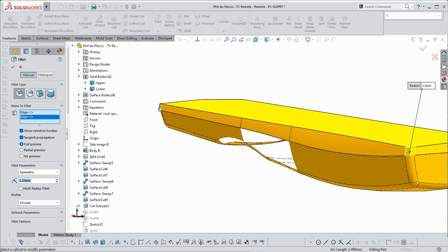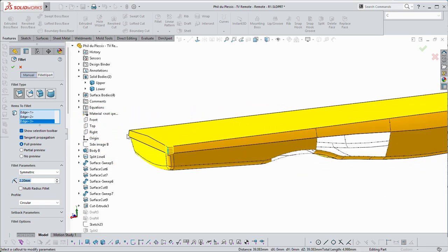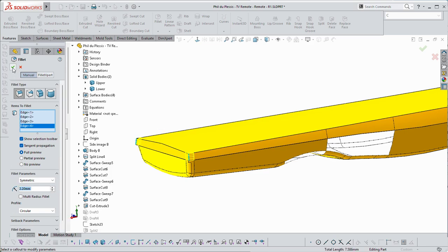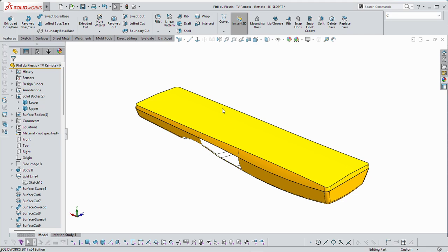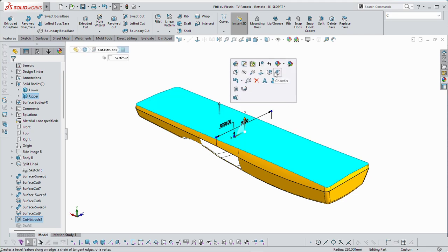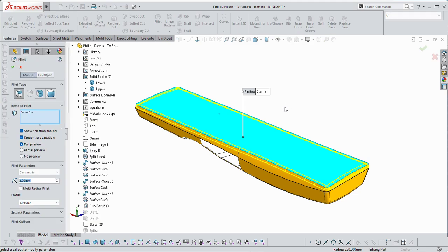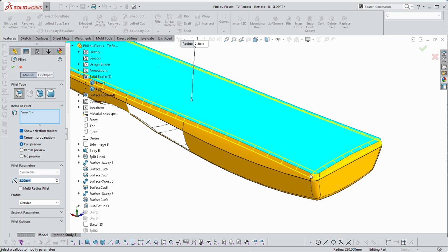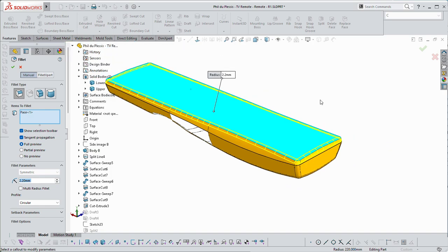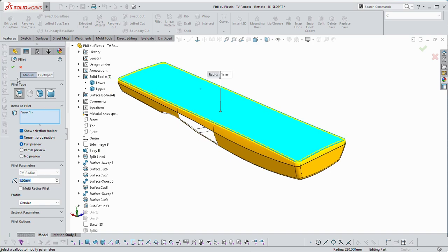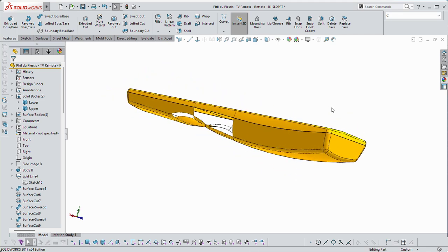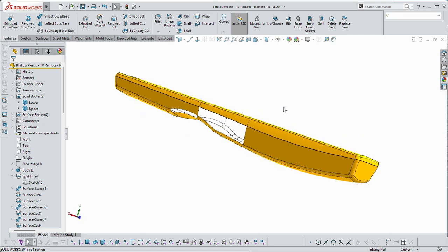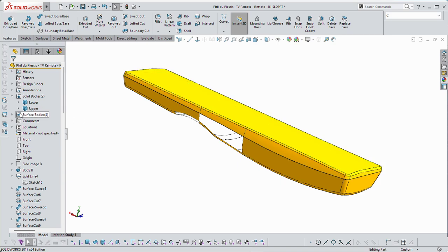So my computer's getting laggy for some reason. Those four, all right. And then the top face, since I don't want to have to select all of the edges, I can just select this whole face and say fillet. And I'm going to give that a nice sharp fillet once again because one, we don't want a three-sided cap, and two, because we want this to be nice and sharp, just because it looks better, in my opinion. Okay, so there we go. We've got two complete bodies, and now we can shell them. This is going to be fun. So I'm going to hide one of these.